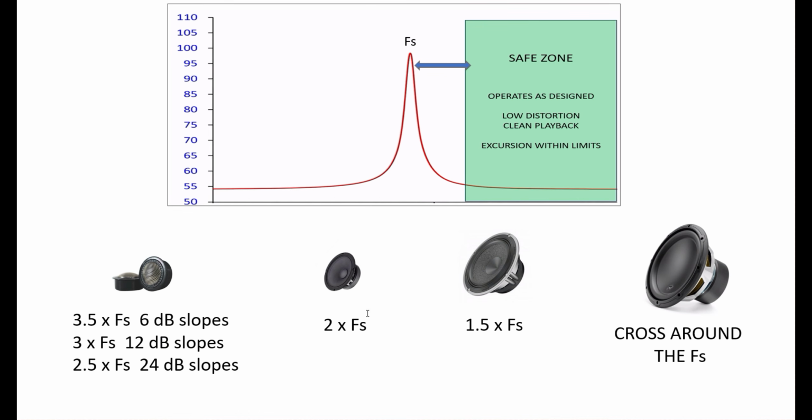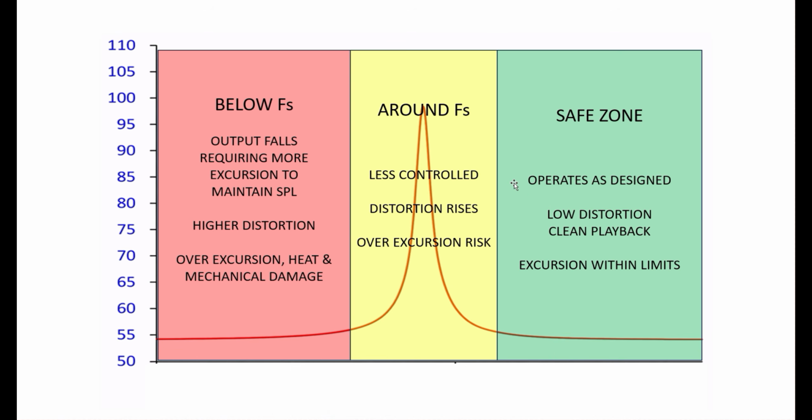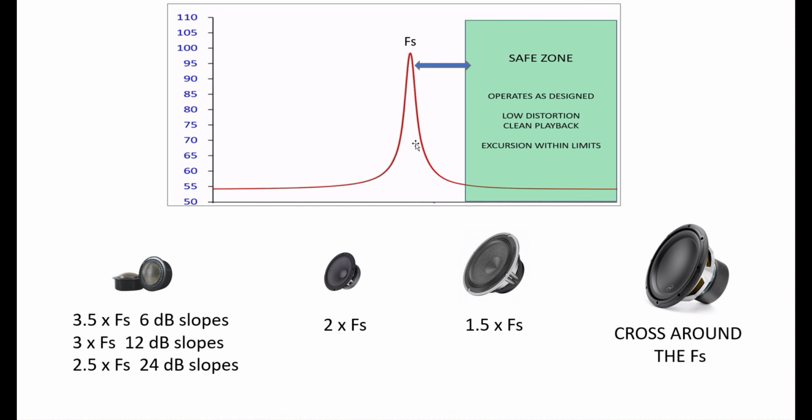Now they're even more forgiving than the mids, but you still need a safety margin for mid bass. I've put in 1.5 just to be conservative, but that's maybe 1.2, something like that. They're certainly more forgiving, but it's not correct to say that you don't need a safety margin for mid bass, because of all of these issues with more distortion and excursion on your speakers and them being less controlled. So a bit like going over the Xmax limit, you can kind of do it, but you'll pay for it in terms of sound quality.